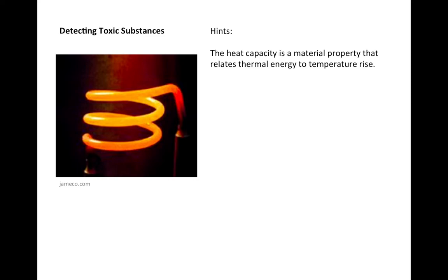Here's some hints. The heat capacity is a material property that relates thermal energy input to temperature rise in a material. Specifically, the energy input is equal to the mass of the material times its specific heat, Cp, times the difference in the initial temperature and the final temperature.